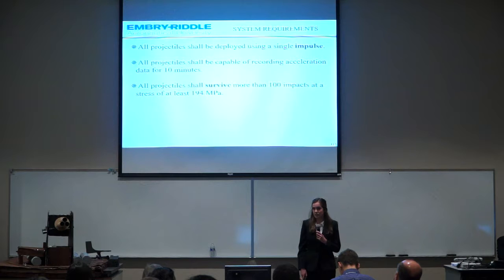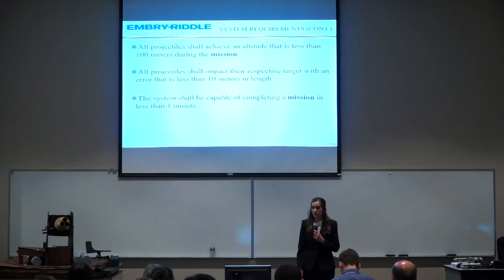All projectiles shall be launched in an impulsive manner. All projectiles shall be capable of recording acceleration data for 10 minutes. All projectiles shall survive more than 100 impacts at a stress of at least 194 megapascals. All projectiles shall achieve an altitude that is less than 100 meters during the mission. All projectiles shall impact their respective targets with an error less than 10 meters in length, and the system shall be capable of completing a mission in less than 1 minute.